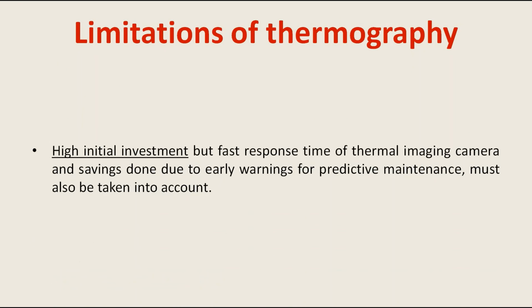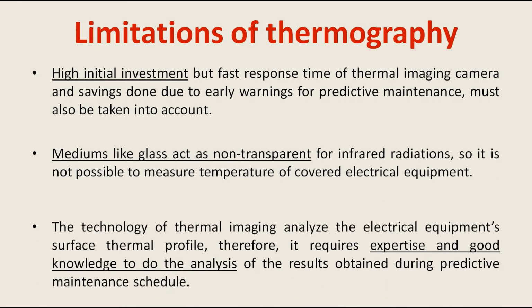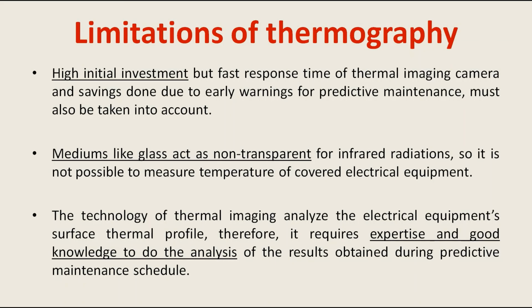The technology also has a few limitations: high initial investment, but the fast response time of the thermal imaging camera and savings due to early warnings for predictive maintenance must also be taken into account. Mediums like glass act as non-transparent for infrared radiation, so it is not possible to measure the temperature of covered electrical equipment.